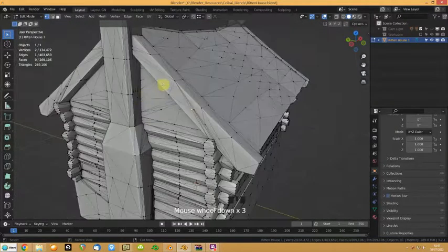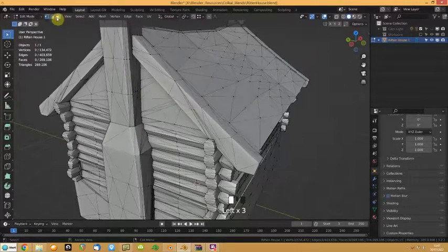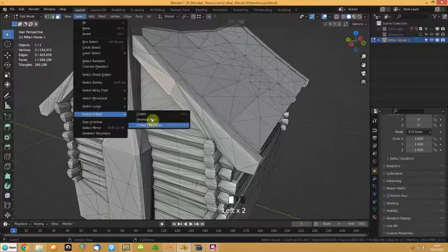I have linked flat faces, so I can select, if I choose faces, by the way that is 1, 2 and 3 on the numbers above the keys. You get your cursor in the viewport, 1, 2, 3, 2, 1, 3, like that, and I can go select linked flat faces, which I have to Shift Control Alt F, which is basically how it used to be set up legacy in older versions of Blender. So it's just a keystroke. Although it's complex, I've become familiar with it. Simple as that.